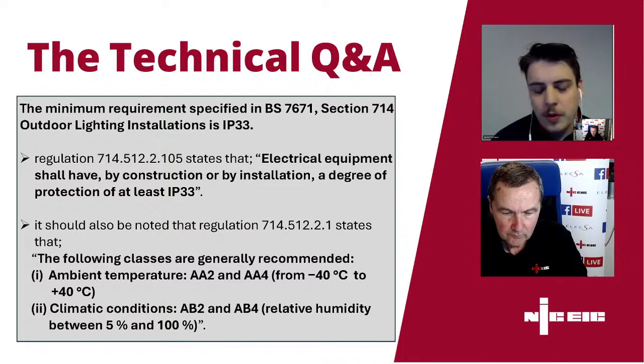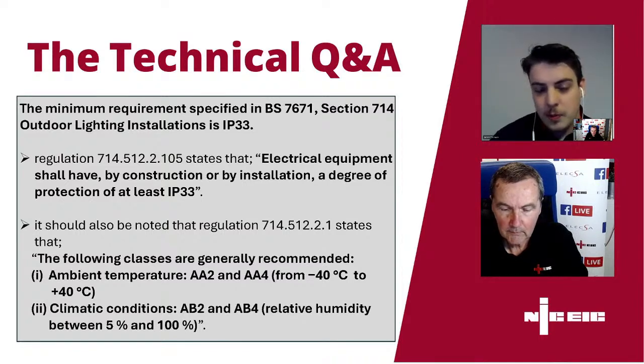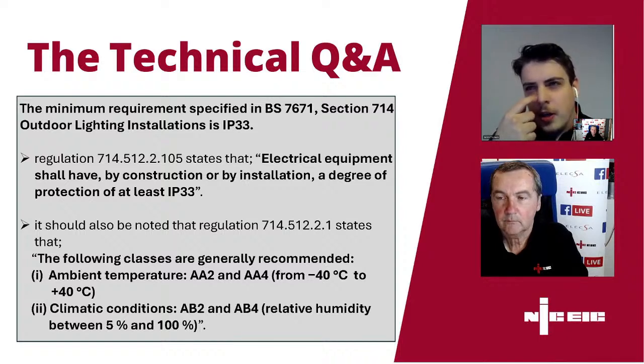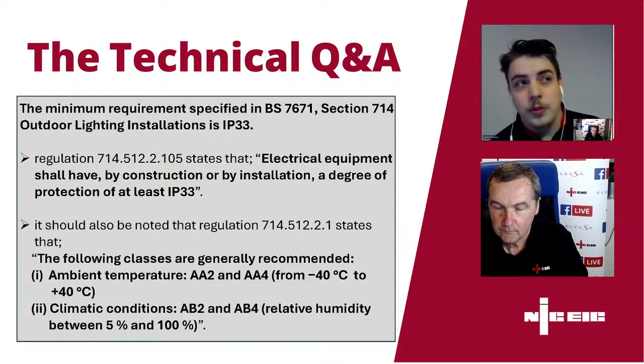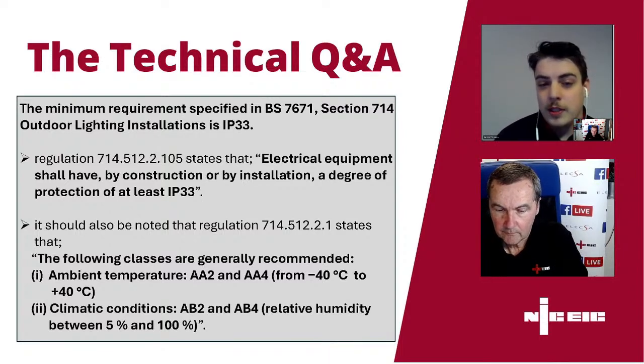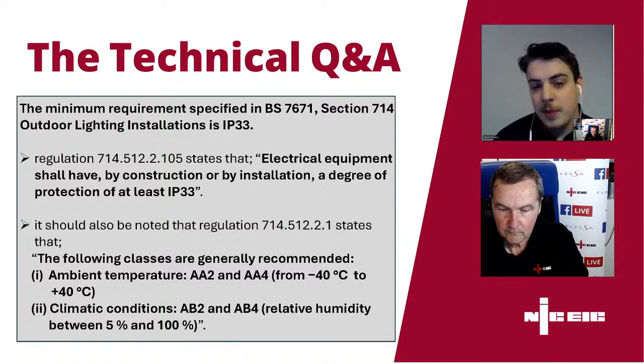I've used that software a lot. When you're creating your certificates on the finalised ones, the little dot on the left, click on that and it will open up 3 options and you can convert to an EIC. I'm assuming by the question that this contractor is a domestic installer, because if he's using the green forms. Yeah. If you're an approved contractor, you can 100% go red to red. So you can do a red EICR, approved EICR, and convert it to an EIC and back and forth.